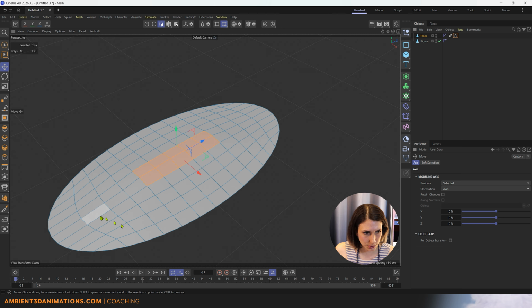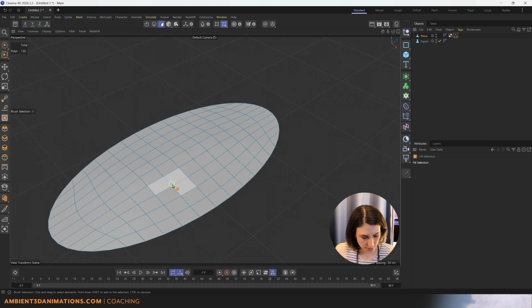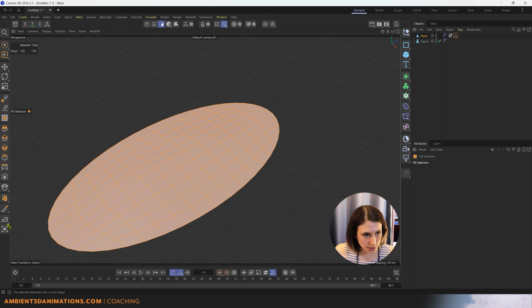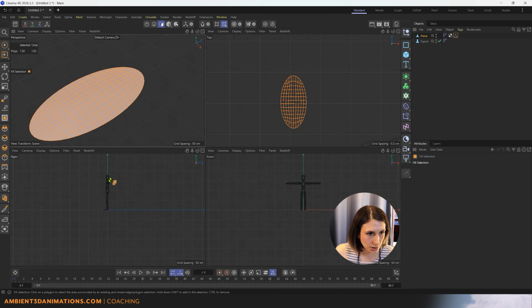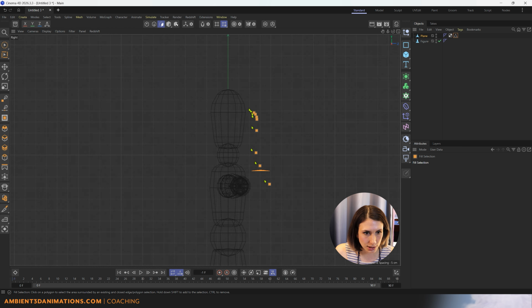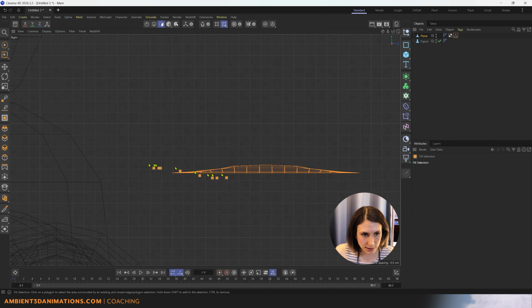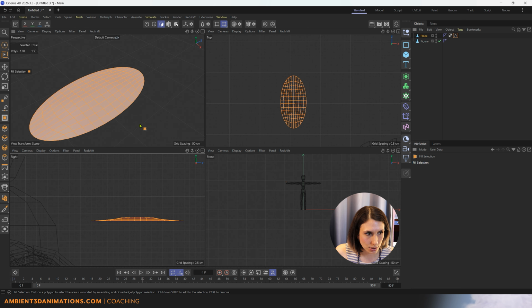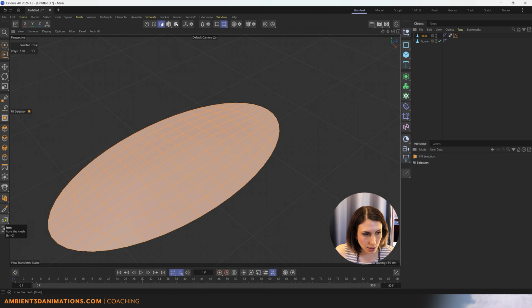One thing that I would say when doing that, UF, just to select all of these in here. One thing that I would say when smoothing this out is I don't really want to adjust this outer edge because right now it's perfectly level. So if I go into the right view and zoom in here, you can see this is perfectly level here. So I actually don't want to be adjusting that outer edge. So if you're going to use the iron, we probably want to make sure we're not selecting that outer edge.